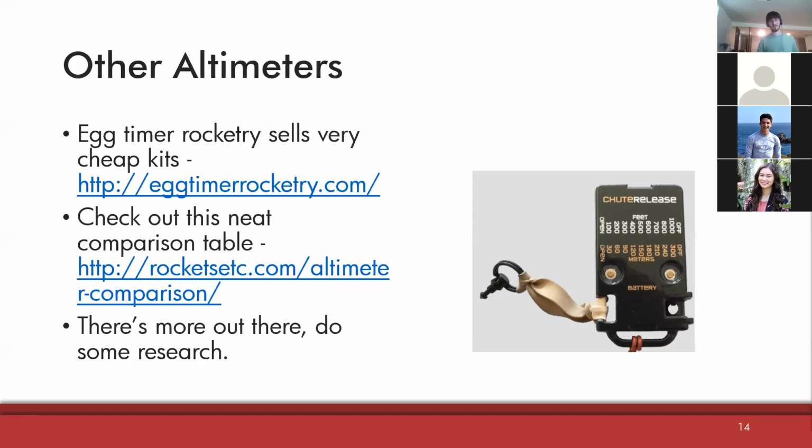But the other thing I have in the picture is a Jolly Logic chute release, which you guys probably all remember from our rocket this year. Just to summarize it real quickly, essentially it's an altimeter that just deploys and unhooks a rubber band around your parachute at a set altitude, so that you can essentially turn a single deploy rocket into a dual deploy rocket.